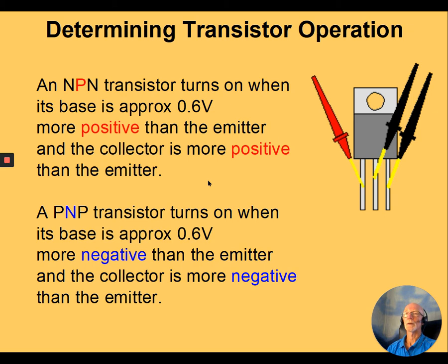Now, as with a diode, the reading we get is what the multimeter is telling us is the forward bias voltage of that particular junction. So if your multimeter says 637, that's telling you that the junction forward bias voltage is 0.637 volts. Some multimeters don't have the point there, they just tell you 637. Others will have a decimal point to tell you that it's actually a voltage.